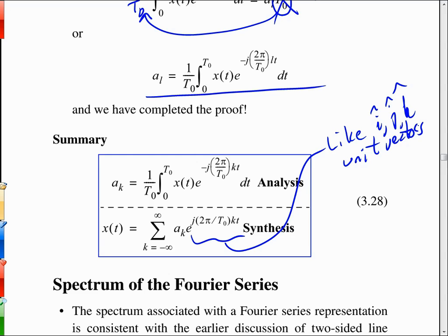If you make the sampling rate used to play the sound back faster, it's going to play back faster and raise the pitch. If you make the sampling rate slower, a lower frequency value, it's going to play back at a slower speed, and that stretches the sound out so the pitch lowers. In both of those scenarios you're getting a pitch shift, but you're also making the information play for either a shorter or a longer time. If you wanted it to play for the same time, that's where the idea of pitch shifting comes in. It plays for the same duration, but you shift the pitch up or down slightly.